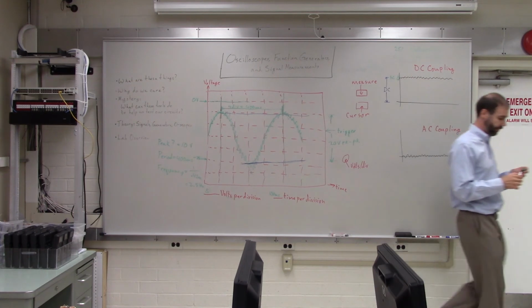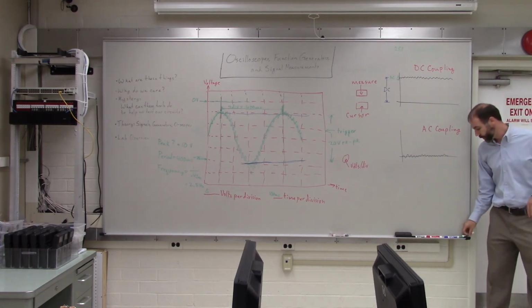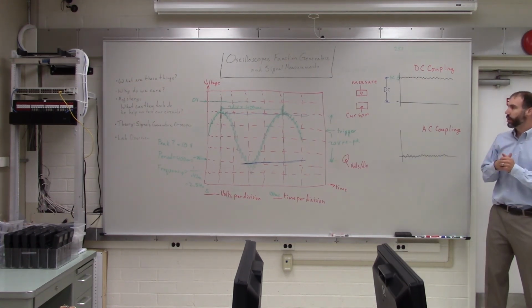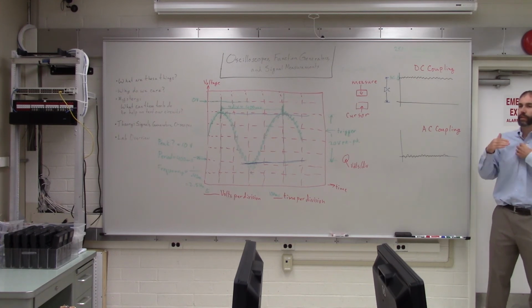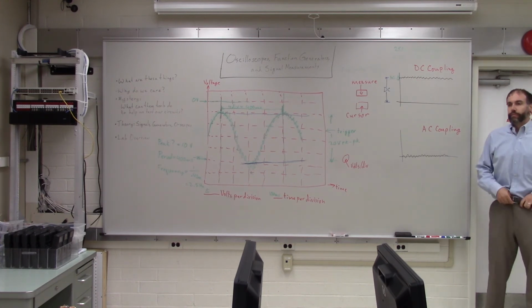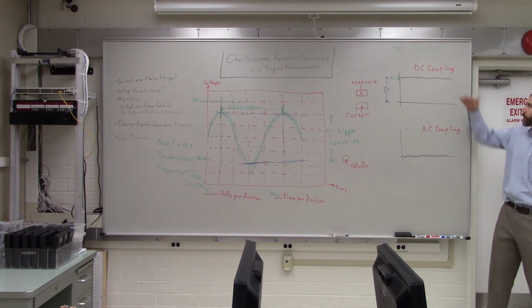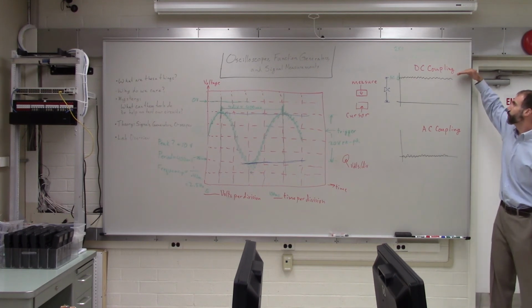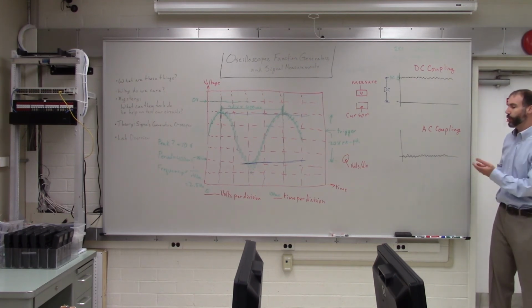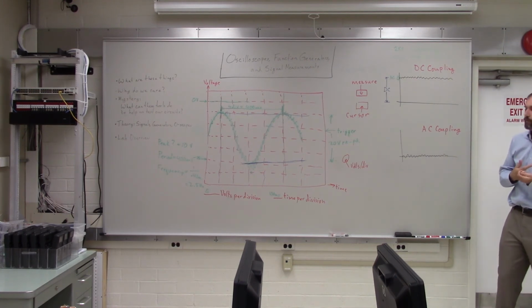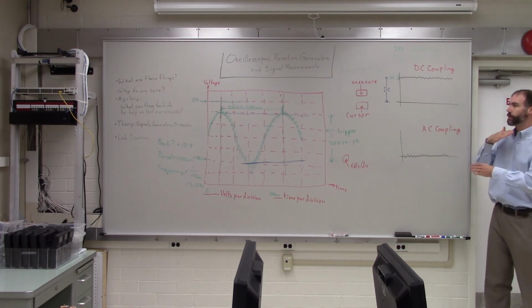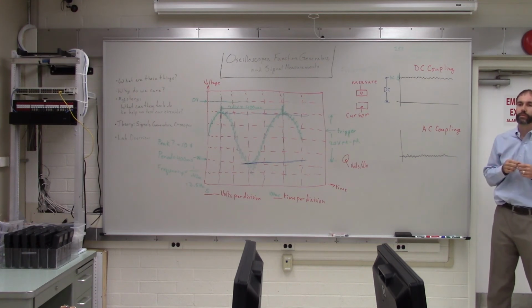So that's useful mostly for finding a signal, finding where your 0 level is. So you can choose what type of coupling you're using. You can choose to have DC coupling or AC coupling or ground coupling. And if you choose to have ground coupling, then it always just sets your incoming signal to be 0 volts.